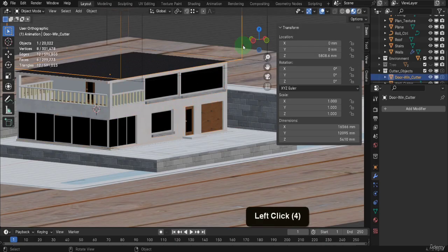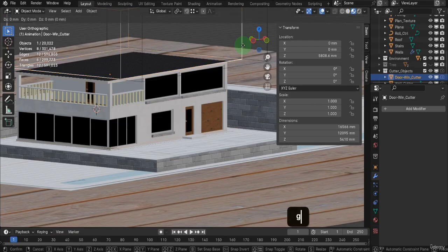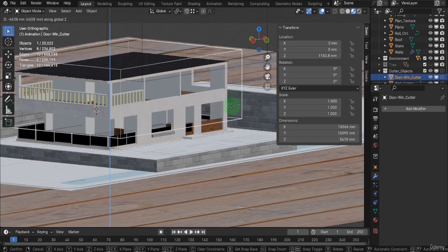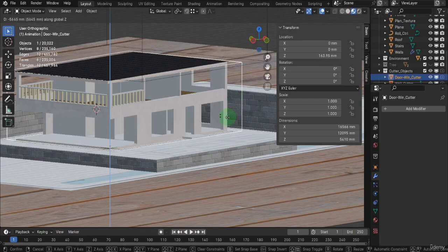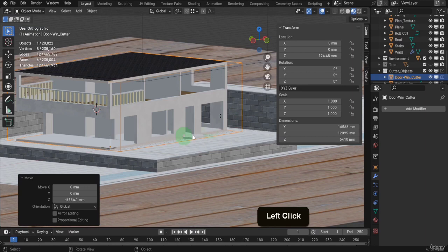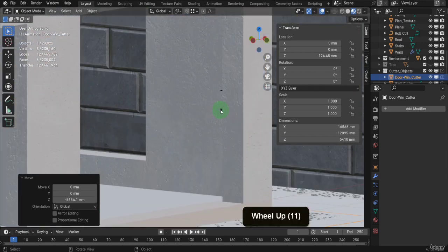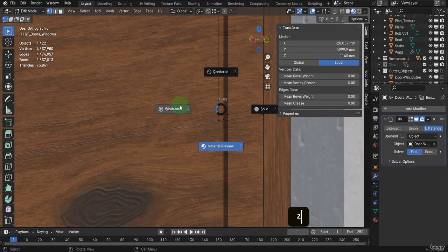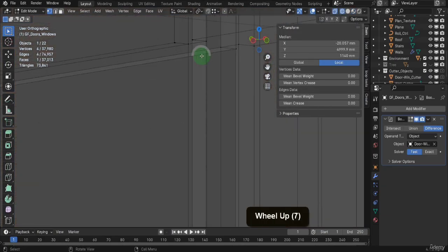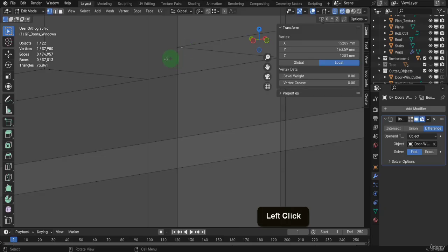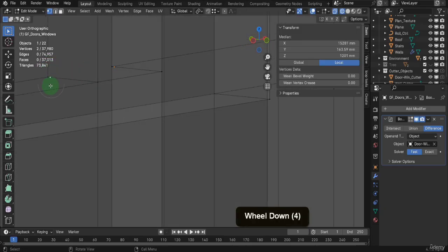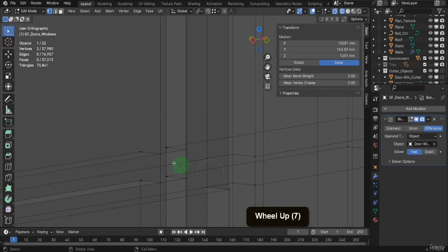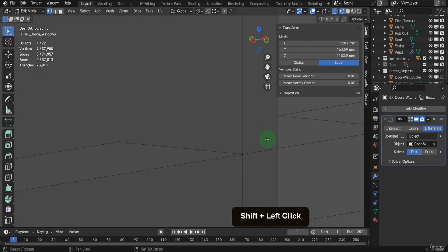If we select the door and window cutter object, press G Z and drag down. The objects will disappear. Some edges become visible as we drag down, but edges don't render, so they will be fine. Here in my file, some artifacts remain, so I'll select these and tab into edit mode. Press Z and switch to wireframe shading also so we can see these. I need to zoom right in here. These are extra vertices created by the ArchiMesh add-on when creating the door. I need to select all these extra single unconnected vertices.